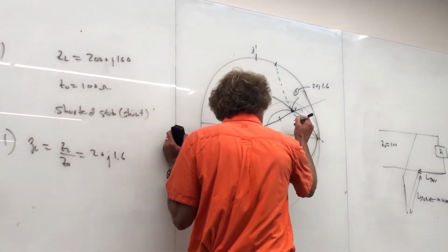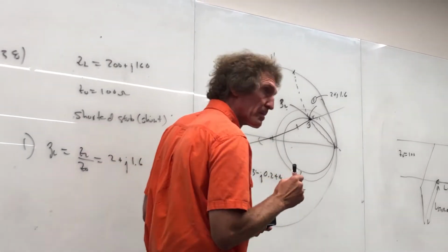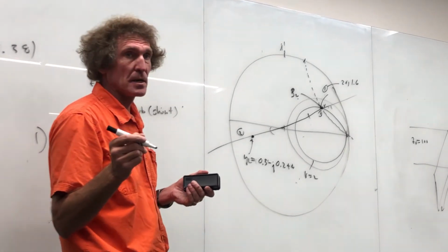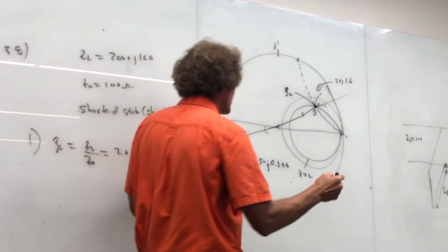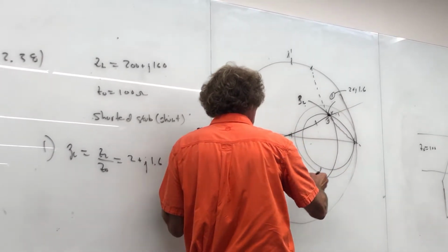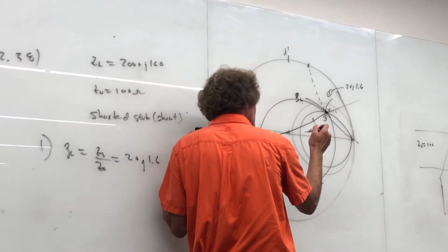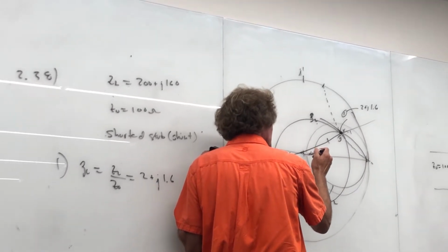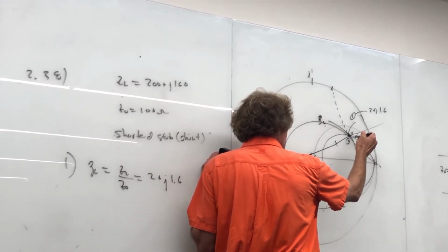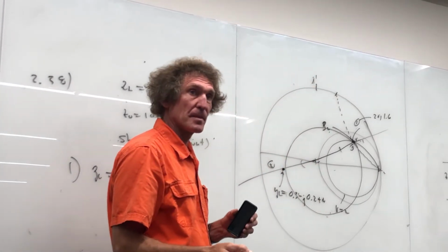And what I'd like to see in the test is a 1 here with a circle, then a 2 here, because now I'm there. The next thing you probably should do is take your compass and make this circle right there. Remember, take your compass point and stick it right in the center of that Smith chart, at 0, 0. Then go out to the point and draw a circle. With me, class? Draw a circle.